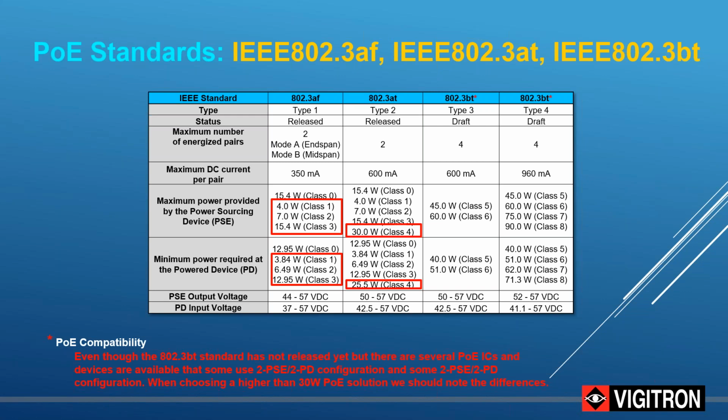But also notice something else. Look at the range of voltages involved. So here again, if I start off within the 802.3 AF environment, and I have a range here between 44 and 57 volts DC, which means by the time it's traveled over its 100-meter cable, it reaches the PD somewhere in a range of almost 20 volts.